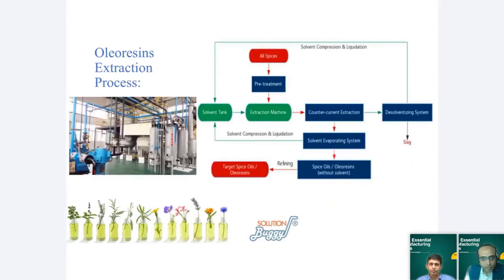So what is the extraction process for oleoresins? Oleoresins are specifically extracted through a solvent extraction process or a CO2 extraction process. The CO2 extraction process gives more precision and more purity compared to solvent extraction, but solvent extraction has higher processability, so you can go with marginal quantities.